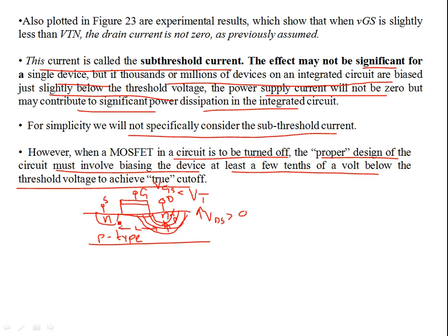it comes in very near proximity to the source. So a situation arises when you keep on increasing VDS, this depletion width is increasing. You're reverse biasing your drain terminal with respect to the substrate, which is p-type. This n-type region grows. I mean, this depletion width grows and becomes very close to the source doped n-type region.